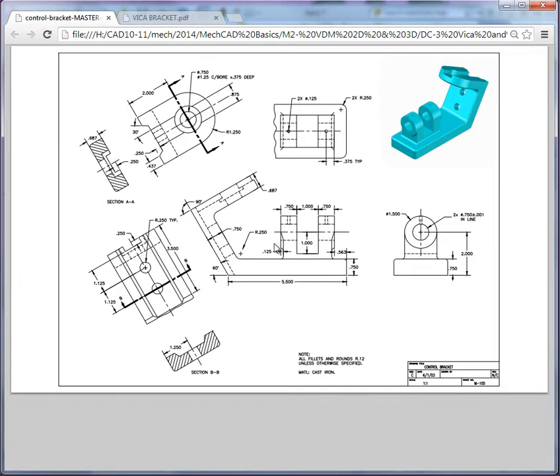And certainly the next one that I can see here is this mirrored flange, sitting on a base. Now, we can certainly proceed to develop these features, but we also have these other face features. If we look at our auxiliary face A and then our auxiliary face B, we can actually utilize the model faces as planes to develop our sketches.